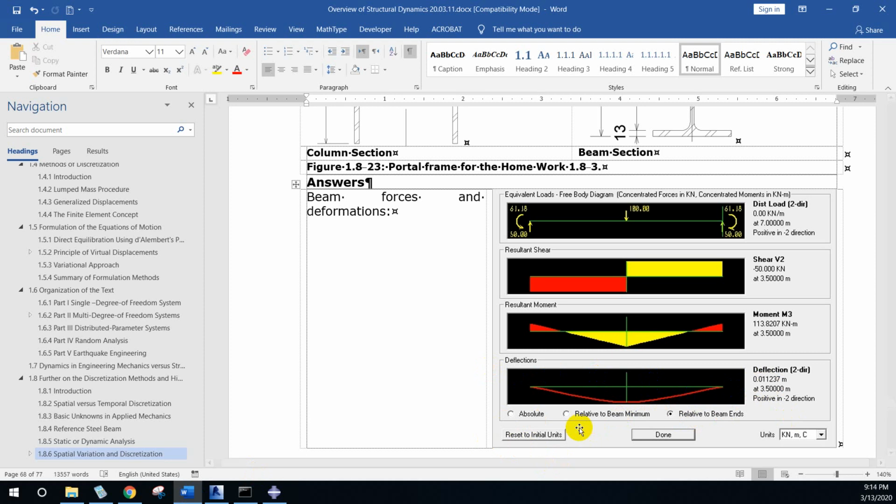As expected, the deflection is closer between the two models, as it depends on the approximation of the function, while the discrepancy in moments is expected to be larger, as it depends on the second derivative of the function.